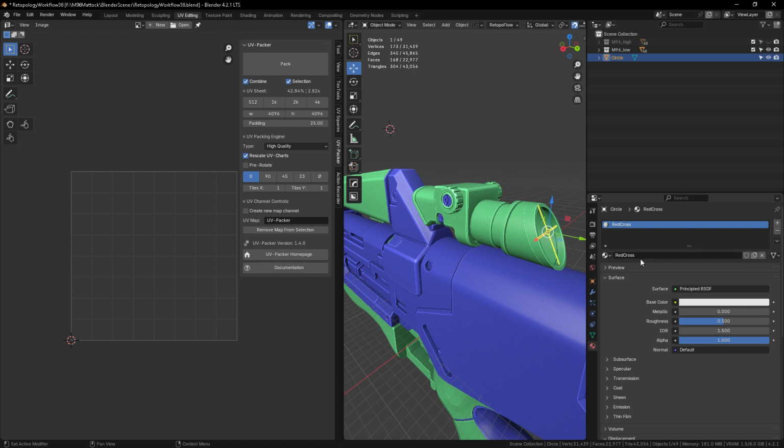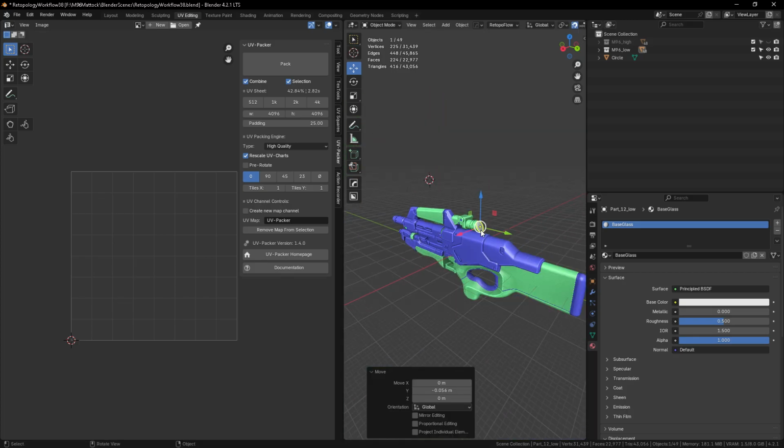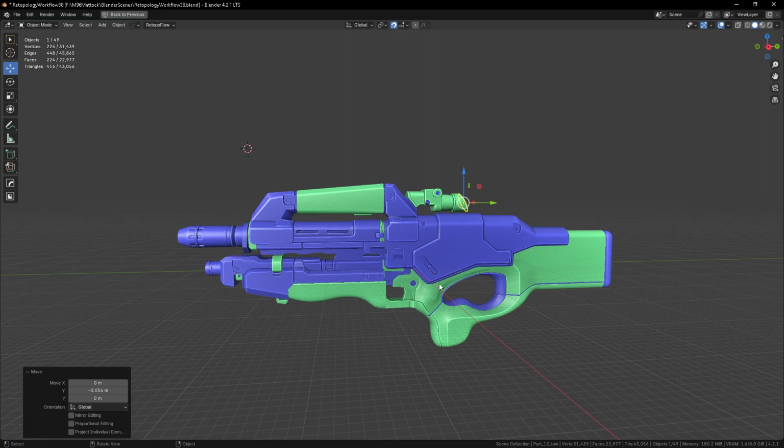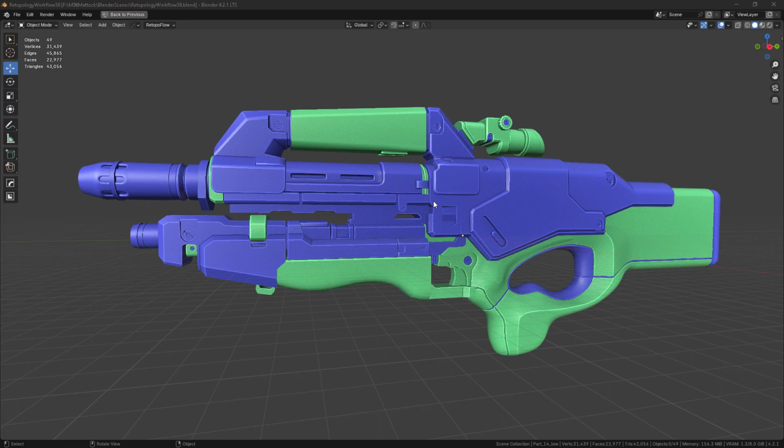Now we need to create one UV tile or more than just one UV tile per material. It depends upon the texel density you want to choose for your islands. Alright, we got our material assigned. The blue one for the metal, the green one for plastic, and the gray one for glass. Okay, but there is an issue creeping through. I know you can't see that now. I'll be showing you in a bit. So we need to address inconsistent texel density.